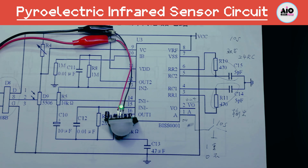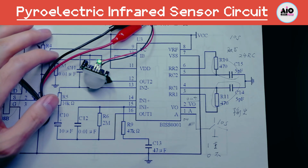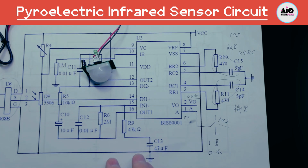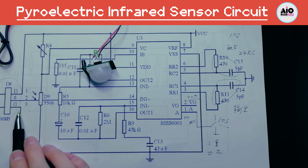In this circuit, its pyroelectric infrared sensing probe is separated from the subsequent amplification part. Now there are some circuits whose pyroelectric infrared sensing probe has been integrated with this part, equivalent to the BISS0001. In other words, its circuit structure will become relatively simple. Now the 3 pins of this sensor are the positive power supply, the negative pole, and the signal output.